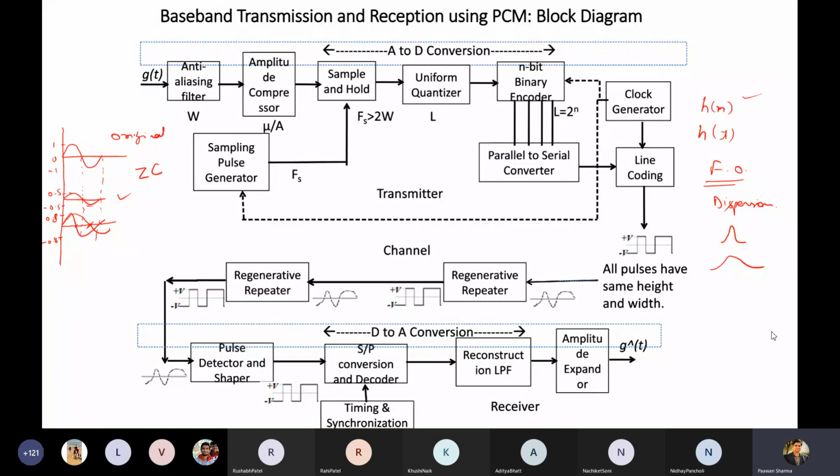So we undo it by using some kind of mechanism which will be exactly the reverse of this impact. So how can we do that? Fiber optics has a model which is transforming this to this. We want to undo it. So we will undo it by using a small length of fiber optics whose system response is exactly the inverse of the fiber optics which was there in this channel. So we will say after 2 kilometers of fiber optics, we will use say 1 meter of a piece of fiber optic which is having a different